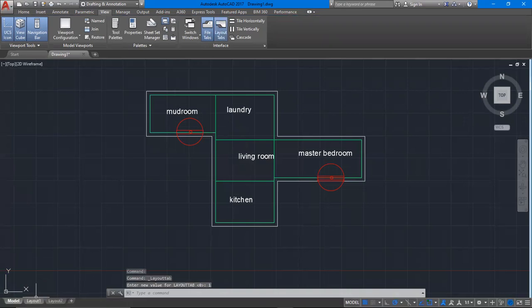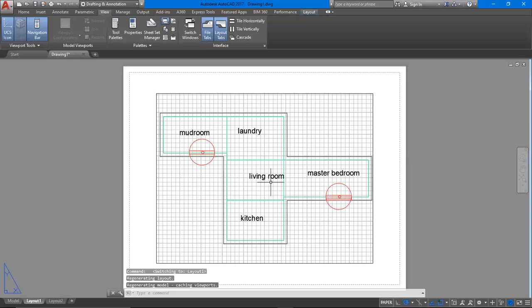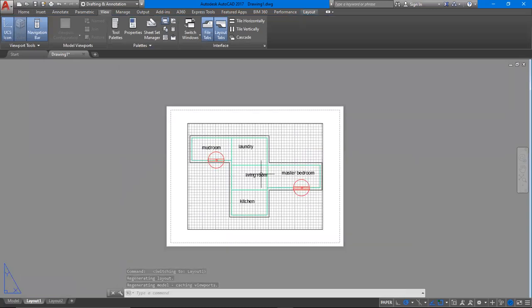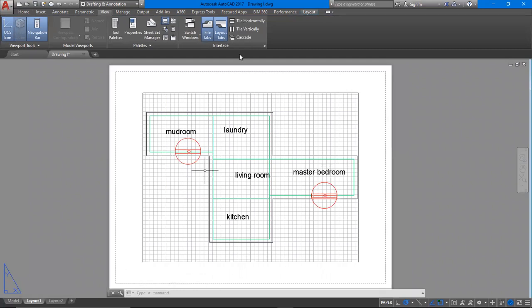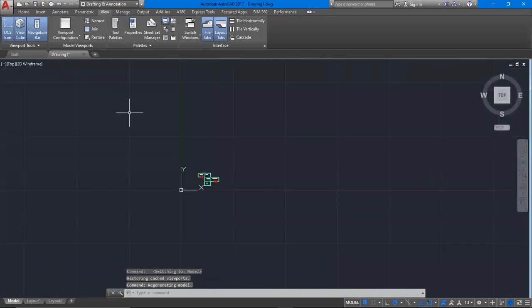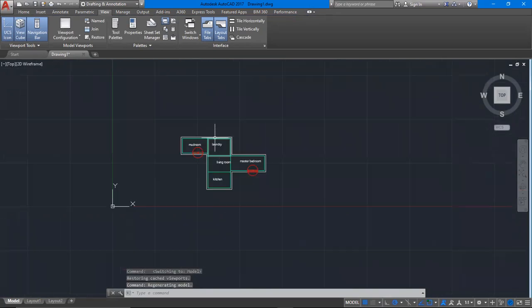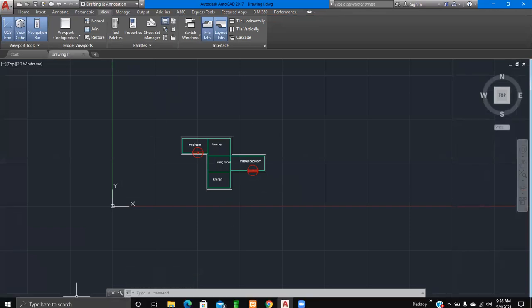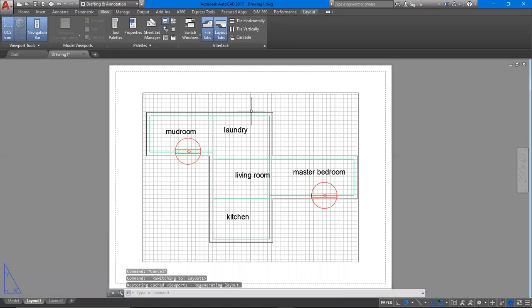And then from here, you can select the layout. And you can see now it has this kind of layout now. The diagram has fitted to some kind of a layout that has some paper size here and a viewport here. So it is different from the model. Model is an infinite space. You may not want to print everything that we have here because this is an infinite space. So when you come to layout, it will just check the space that you have worked on, and it can crop out the unnecessary infinite space that you don't need.